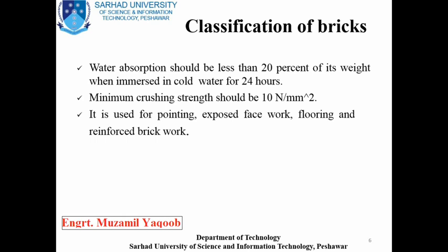The next point is about water absorption: it should be less than 20% of its weight when immersed in cold water for 24 hours. In other words, it has a water absorption capacity of nearly between 12 and 15%.